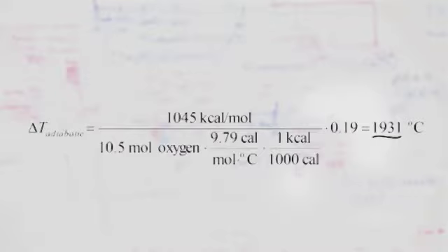In reality, a steel reactor system would melt at this temperature. Since the system is not truly adiabatic, a significant amount of heat would be lost to the surroundings. Of greater concern is the pressure rise that would accompany this temperature increase. We can use a simple ideal gas law calculation to evaluate this pressure rise. Remember to use absolute temperature in this case. When we calculate the pressure increase, we can see it is only about 1,229 PSIG.